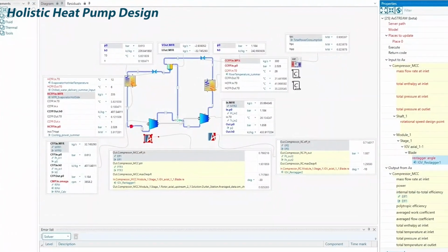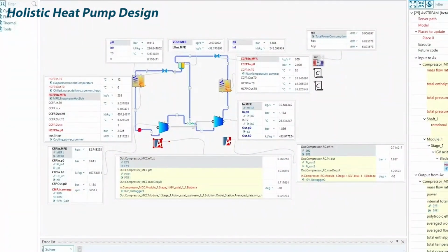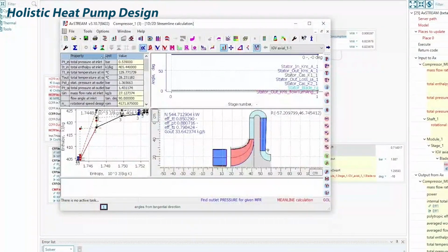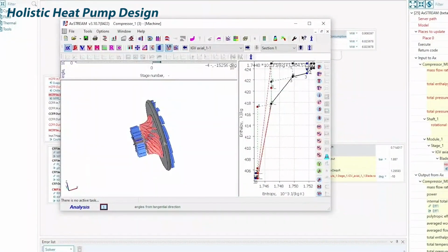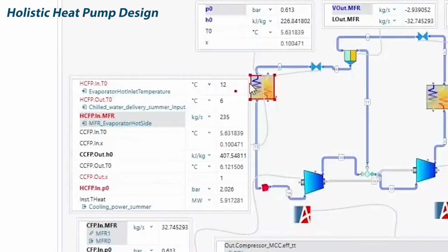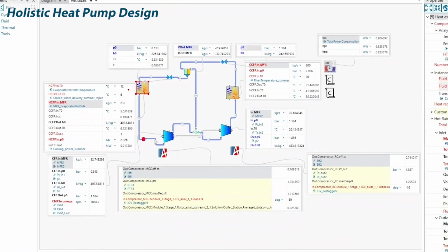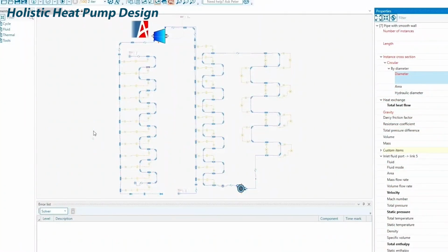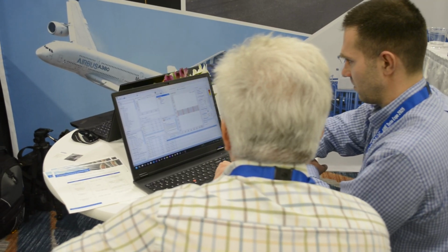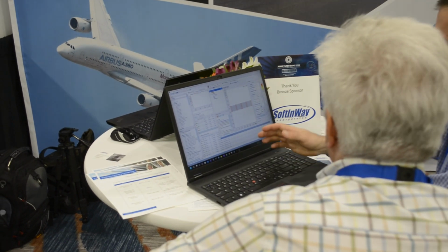When you model everything at once, you get to see that the pump is not working well, so this is why we have those results down the road, or we have some fouling in the heat exchanger. And you get to investigate this to see what's going on and what impact that is currently having on your performances, so you understand what's going on, and you can also do predictive analysis for if I have 3 pumps and one of them fails, how is that going to impact everything down the road?